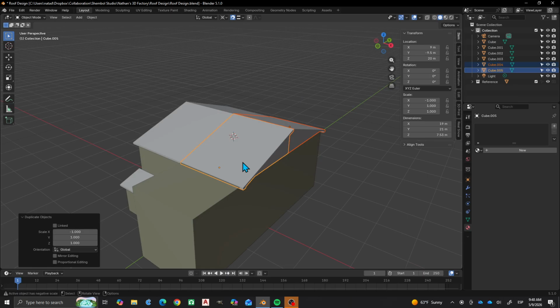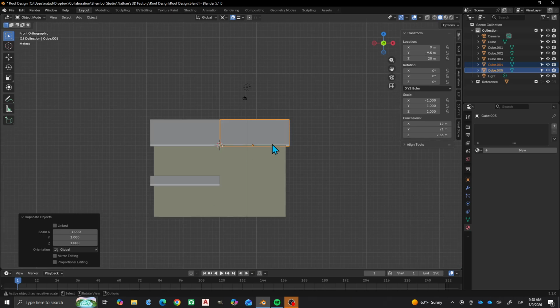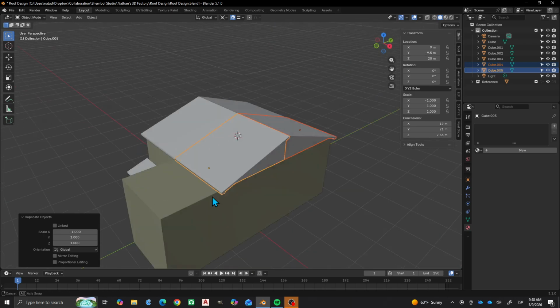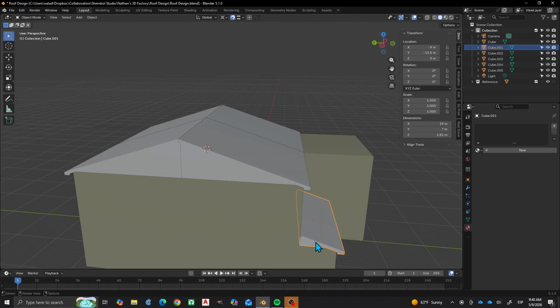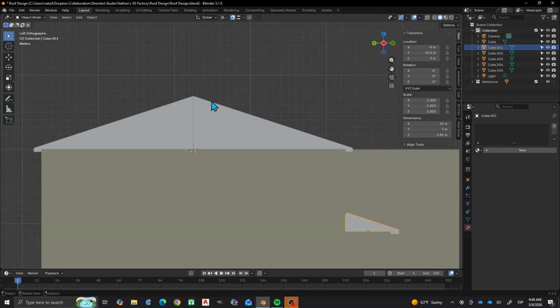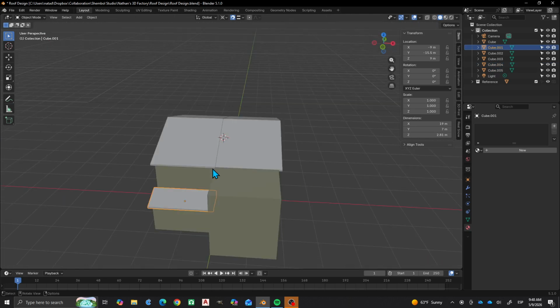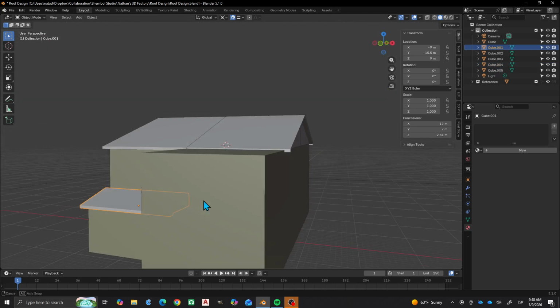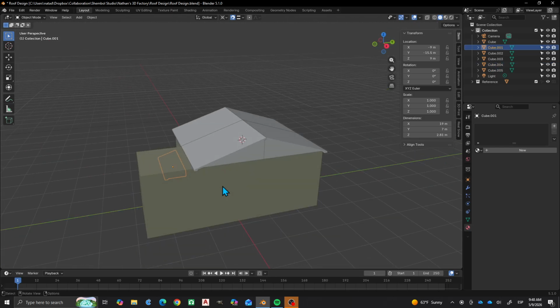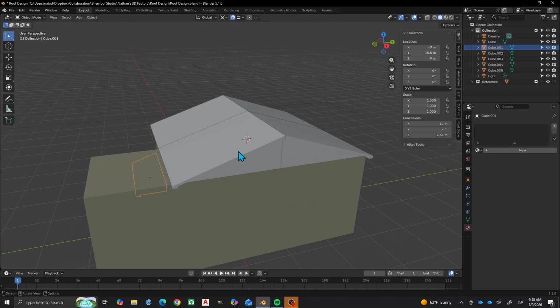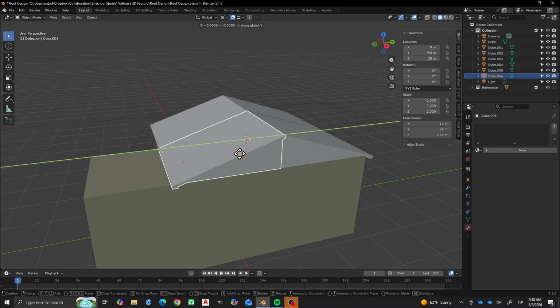So, next thing I would like to do is have a gable that goes right here at the front. So, okay, I'm talking about a gable now. So remember, we called this one a shed? When we have the two-sided, the very typical roof that you'll see on a lot of houses, these are called gables, right? And so what I want to do is have a gable that's going to go up front and do the same thing, right? So I'm going to take this, Shift D, Y.